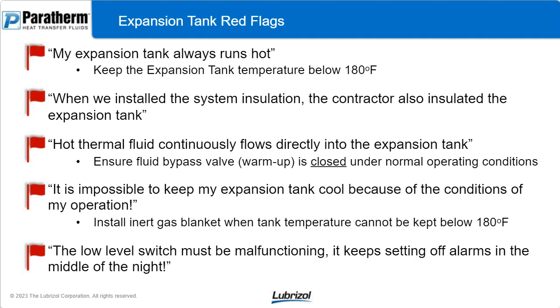So the low level switch, I can't tell you how many times it sets off an alarm in the middle of the night, somebody has to go reset the system, so they end up just deactivating that switch somehow. Don't ever do that. Big problem if you run low on fluid volume. That's a good way to cause cracked heater tubes, and that's where flashpoint becomes a problem again. Always make sure it's functioning.